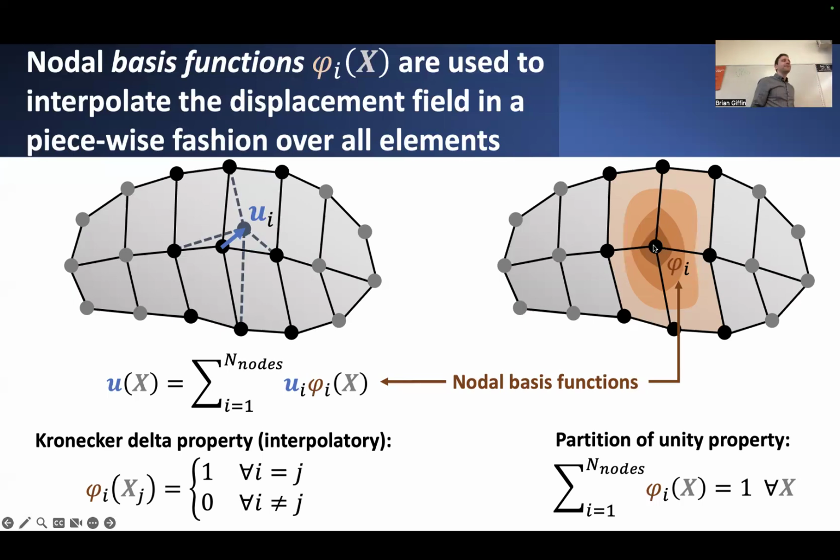So that's kind of the visual interpretation of what one of these basis functions might look like, such that it satisfies these two properties. And I think there was maybe even another one. But the main ones that I want to point out are that finite element basis functions have to be interpolatory. They need to actually recover the specific value of the displacement field when I plug in x sub I, basically. When I try to evaluate the displacement at this particular nodal location, I should recover precisely this discrete nodal value, which basically means that if I were to define these basis functions in this way, they should satisfy this condition, that they're equal to 1 at whatever node they're directly associated with.